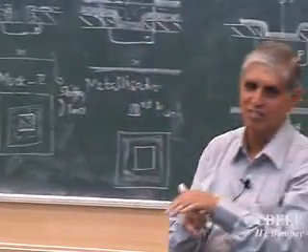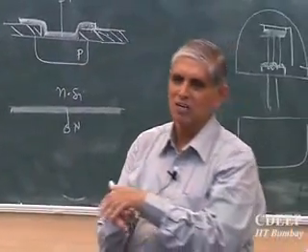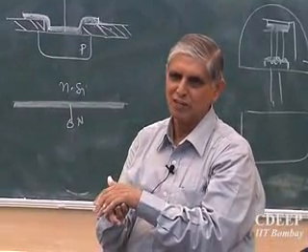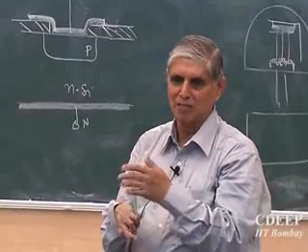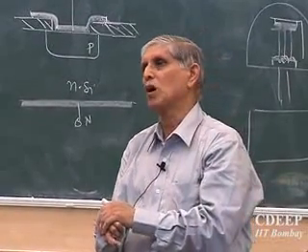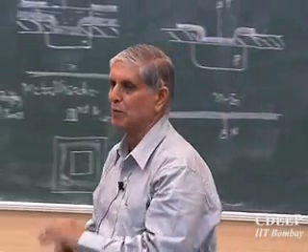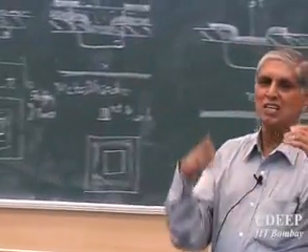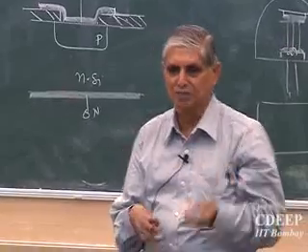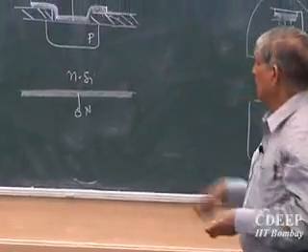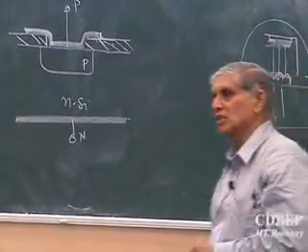It is called lithography. Using light, we say it is photolithography. If the resist is exposed by electron beams, it is called electron beam resist. It's called polymethyl methacrylate, PMMA, if someone wants to know. So this is exposed by electron beams and it hardens or softens, depending on the kind of PMMA I use. Is that clear? So how do I make a diode? Yes.